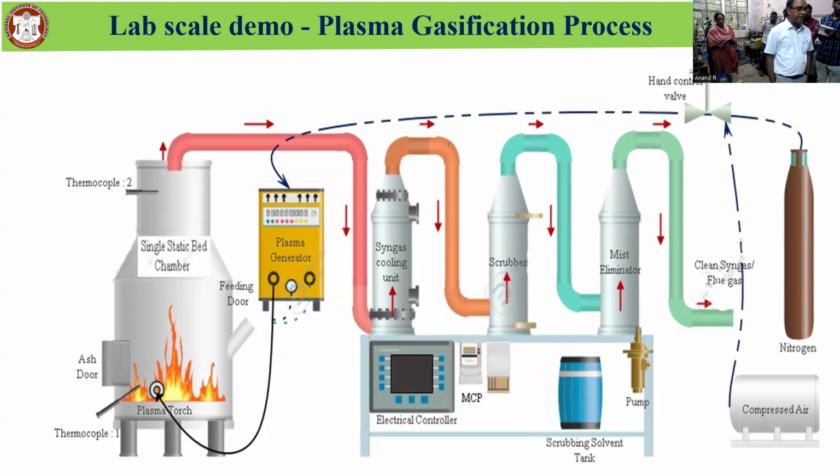The system is operated in 3 different modes. We can operate in combustion mode, gasification mode, and pyrolysis mode. What is the fundamental difference among these? It is about the air quantity we provide. In the general oxidation process, we provide oxygen slightly more than needed for complete burning of the raw material we have used. So we have the flexibility.